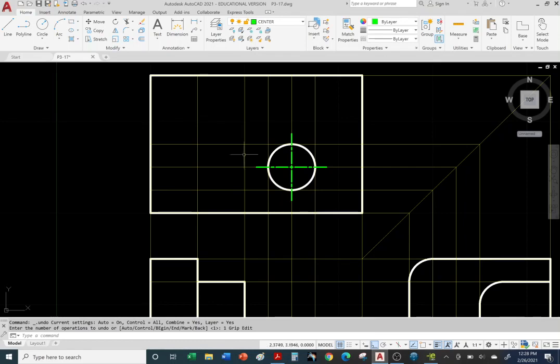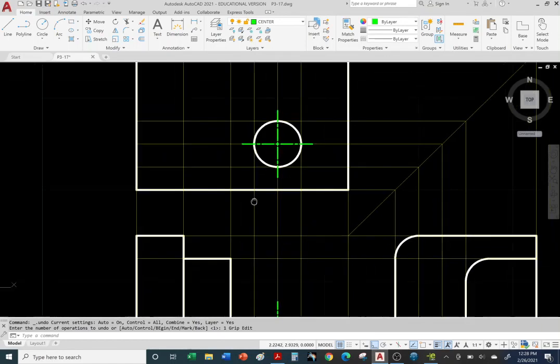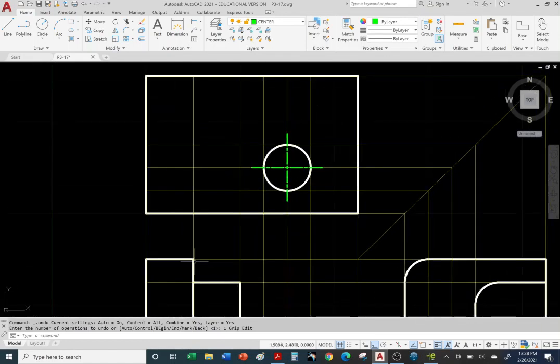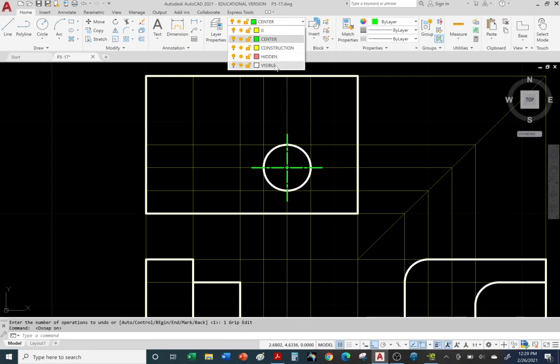All right, so let's go back to AutoCAD. Okay, so let's go ahead and complete the top view. Okay, so from this corner here, from the front view, we're going to draw a line straight up, right? Okay, so let's go ahead and turn on Object Snap. And let's go to the white visible object layer, and use line command.